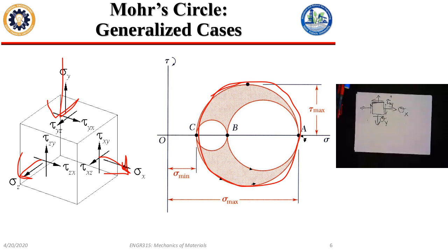Yeah. So we're always drawing the circle, we'll always draw the x, y. Those are the two stresses that we can solve for by cutting sections. Then you look at your sigma z, say, okay, it's 0 or whatever.